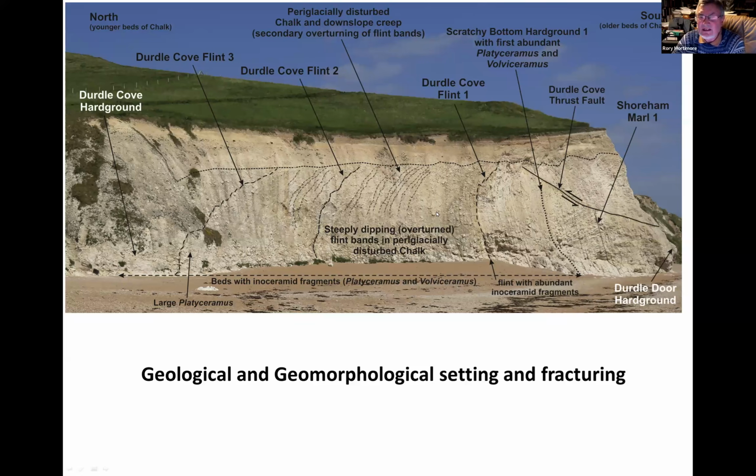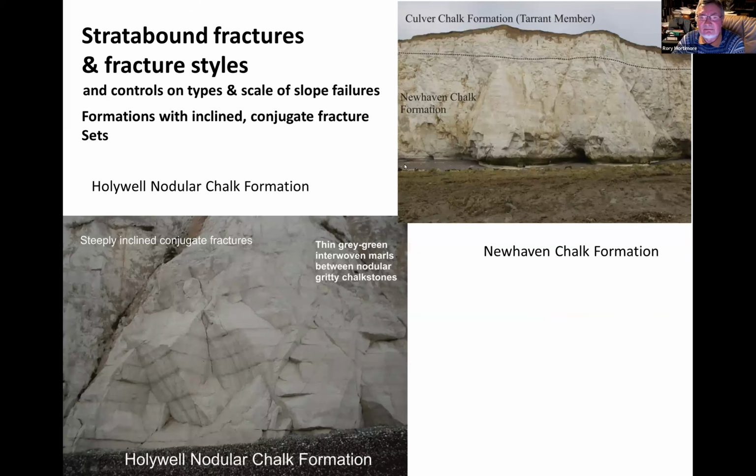But you can see how deep below the ground surface the chalk is destructured. It's lost its true bedding structure, and you have a problem in trying to decide where it becomes a structured chalk. But you can still pick out all the layering going all the way through, and you can trace the layering moved down slope by the creep.